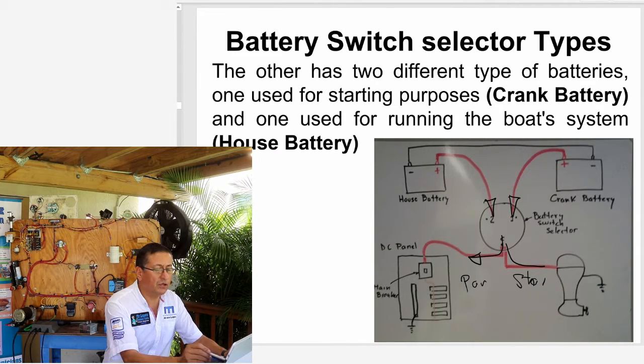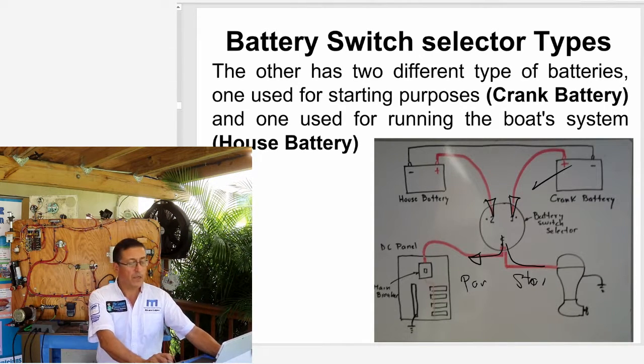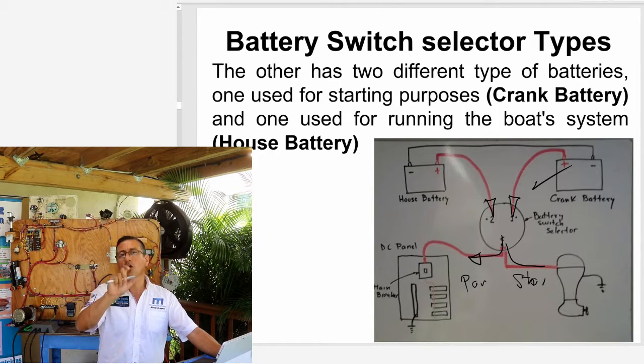Okay, this is good. This type of battery switch selector is excellent when you use the cranking batteries only to start the engine, and after that you switch to the house battery.